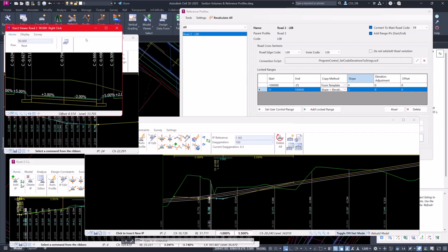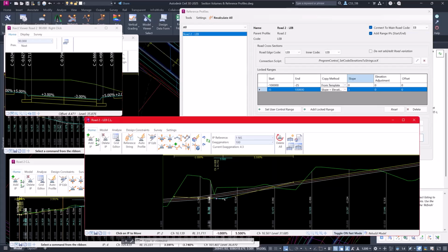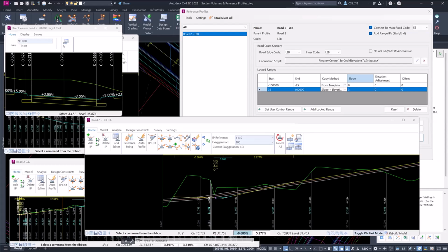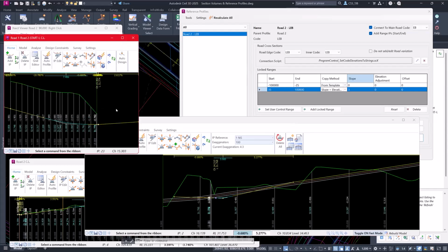And maybe I want to do some more, be an effort for me to come in here and start making some changes in here. But as I said, I can manipulate all these things to change around all of the stuff that might be useful. So I could actually come in here and go, oh, maybe I want to change this. So drag it up a little bit, see if that has any, oops, not far enough, has any influence. Maybe I'm dropping it too far, but I've got to be mindful that I'm making that too flat. But I'll do that, recompute, see what it does on my curb return. There you go. Still pretty good. Low point's still sitting at the end. Perfect. Achieved my goal.